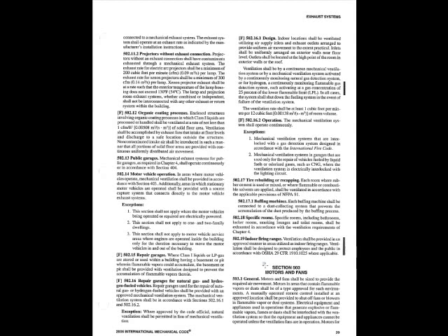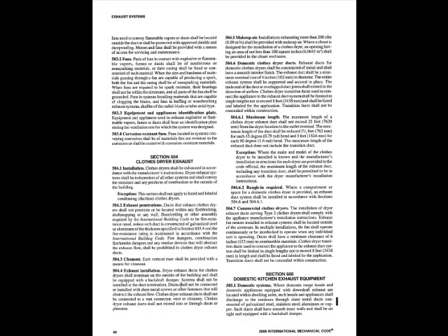Section 503 talks about the motors and fans, what the requirements are. It starts off with saying motors and fans shall be sized to provide the required air movements. It also specifies that motors in areas that contain flammable materials and dust shall be approved for such an environment. We don't want to create sparks. Fans are discussed, and the equipment and appliances identification plates are required. In certain areas, we must have corrosive resistant fans.